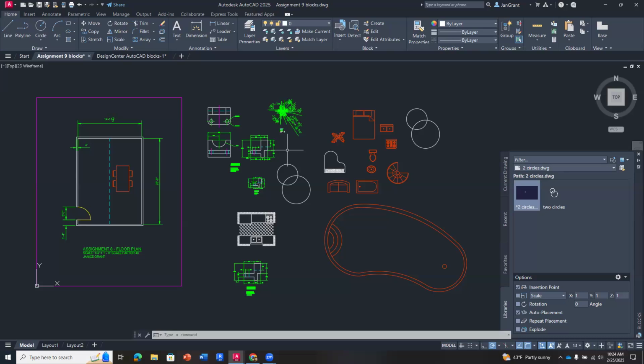But there is this theory, it's not a theory. I've used it for about 10 years and companies are using it. It's called XREFs, or reference files. So if I reference a file to this file, I'm not inserting it, it's a link.